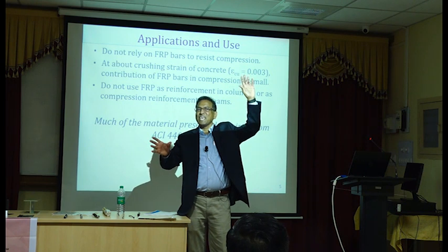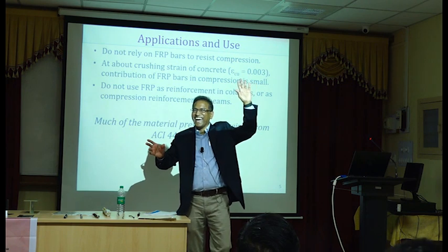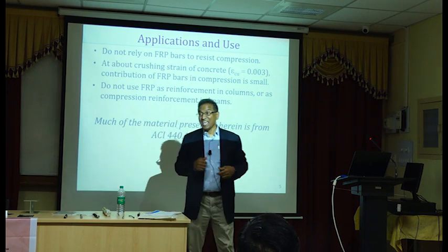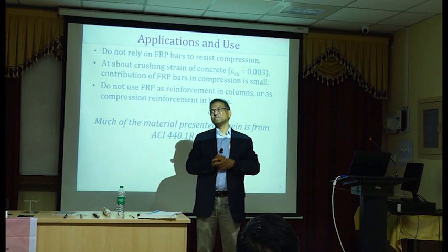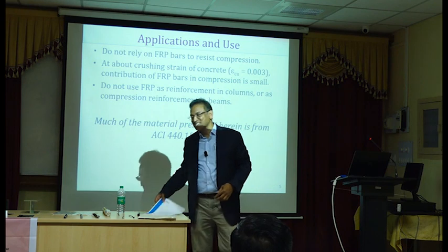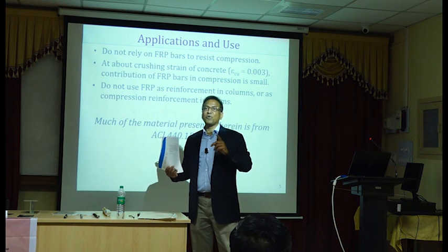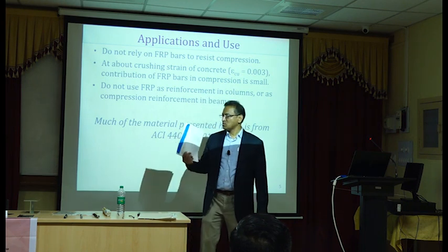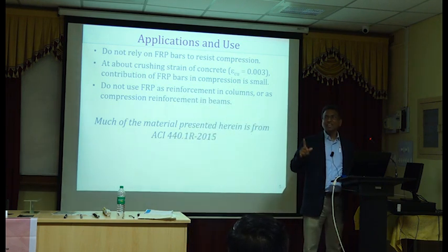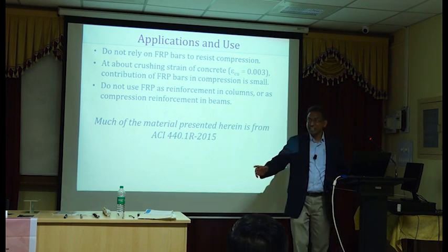So you will be safe or unsafe using cylinder strength? It can be either safe or unsafe, right? It will be unsafe by 20% to 25%. Very, very important. I just really wanted to highlight this to you, because this is all based on cylinder strength. Eurocode has already switched to cylinders. I don't know about British standards, but Eurocode has switched to cylinder strength. So if you are designing using cube strength, you already have 20% reduction in your safety.